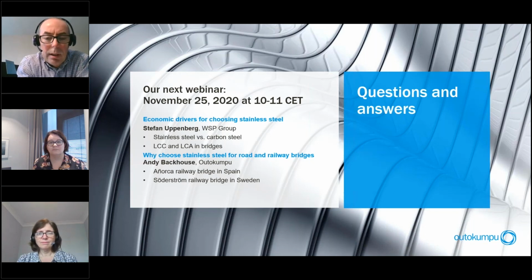Particularly if you have an architectural feature, then surface finish can be more important, because smoother finishes tend to trap salt and pollution less readily, and they are more readily naturally washed by rain. So a smoother surface finish is generally less susceptible to minor tea staining, which is a superficial discoloration of the surface.